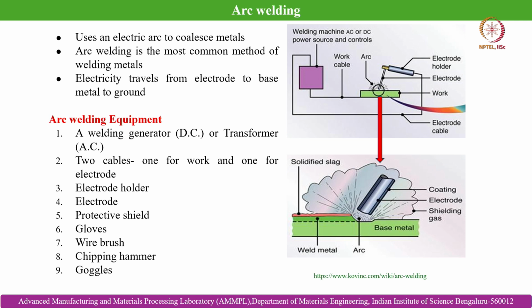It is a typical example of autogenous welding, where we are basically subjecting the workpiece to fuse in joint preparation, whereas in case of metal inert gas welding we are basically consuming the electrode as a filler material in joint preparation. That is the difference, but otherwise their working principle is the same.